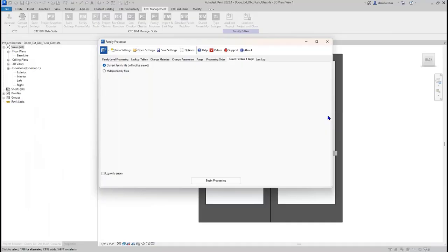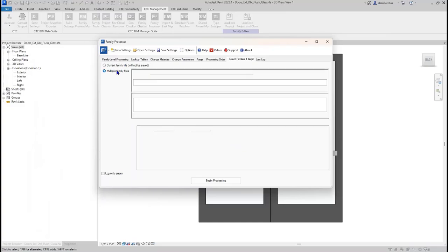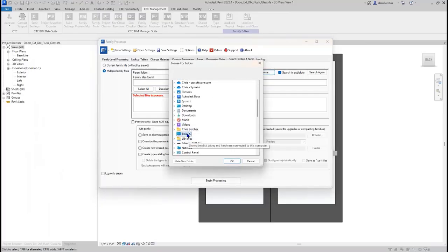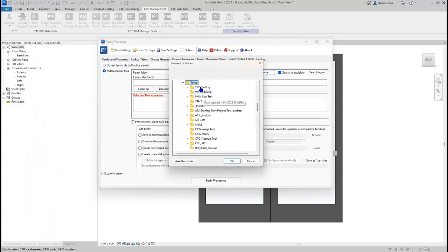And just make sure that before you apply this across the board to all the families in your library, you can check it. Once you've established that, yes, this process is going to work, you can save your setup to a settings file to be used later on, and then turn around and pick a folder's worth of content to apply your changes to, whether that's one, a couple families, or all of your families, right?